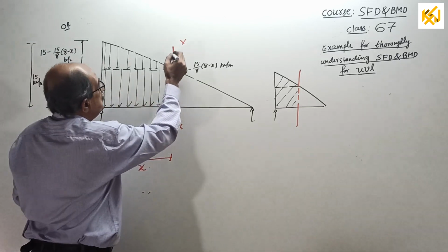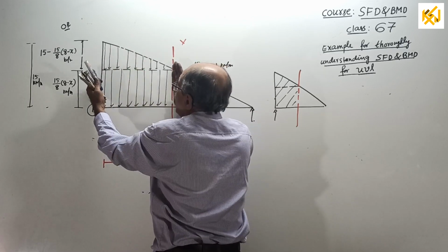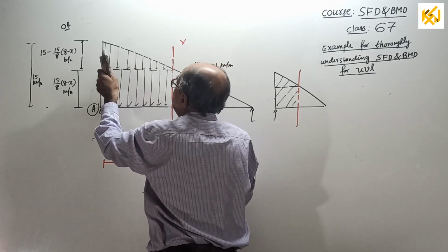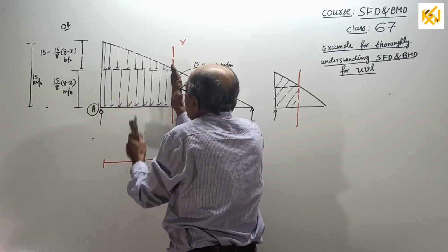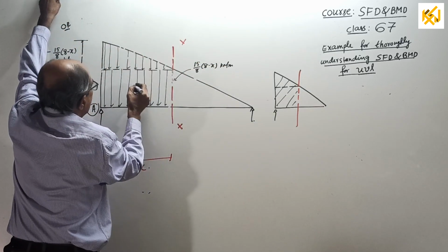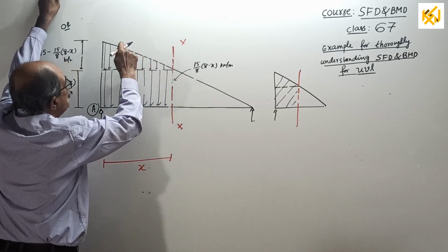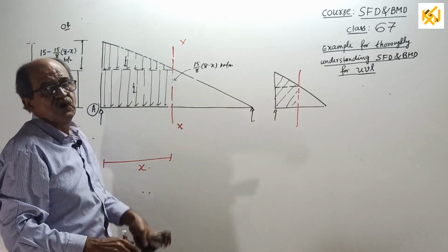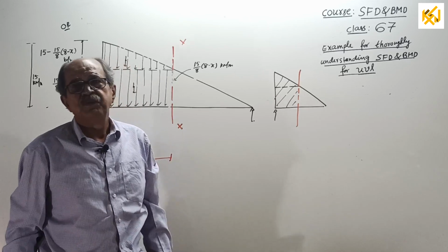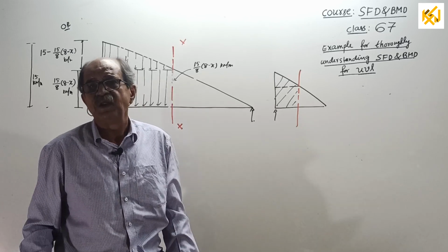Then remember, when you take shear force here, take this load and this load both. This load is a rectangle UDL, that is x into this ordinate, here half into base into height. Moment for this UDL, distance is x by 2. For this uniformly varying load, the CG will be here, 2 by 3 of x. So I will solve both ways so that everybody who is used to only rectangle and triangle, who do not want trapezium, can use my class also for further learning.